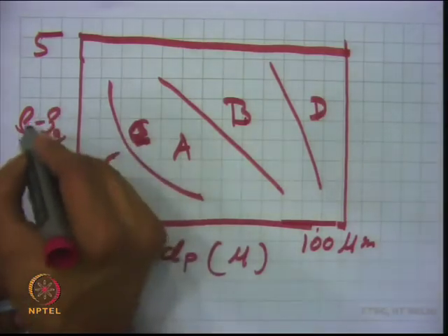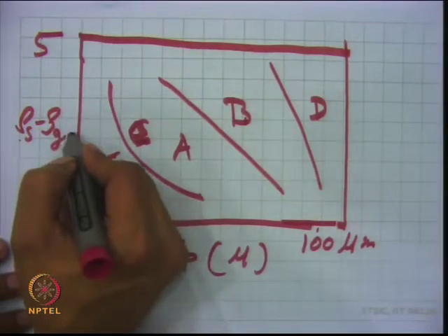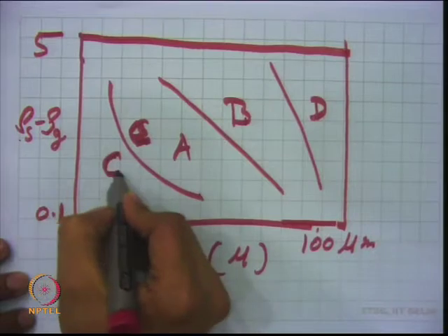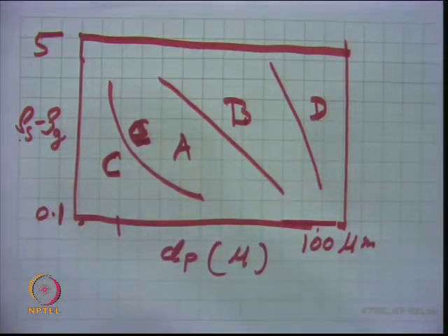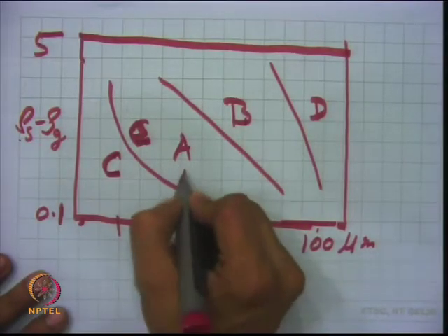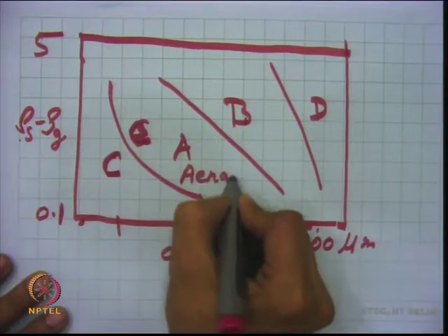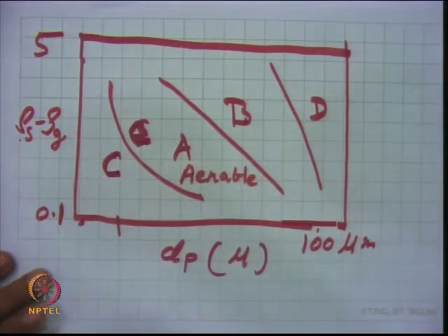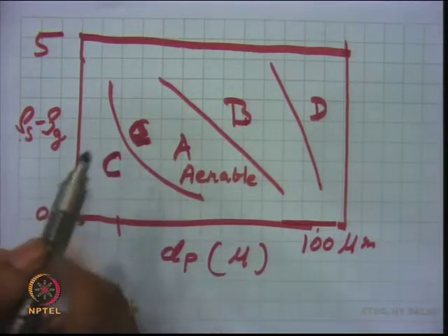And this side is the density of the solid and density of the gas. Depending upon this, one can select a definite condition required for fluidization. Particle size is important, the physical properties of the solid material are important, the gas is important, and the viscosity of the medium is also important. This is what I am calling the bubbling or aeratable particles, one classification where the bed expands and then forms bubbles.